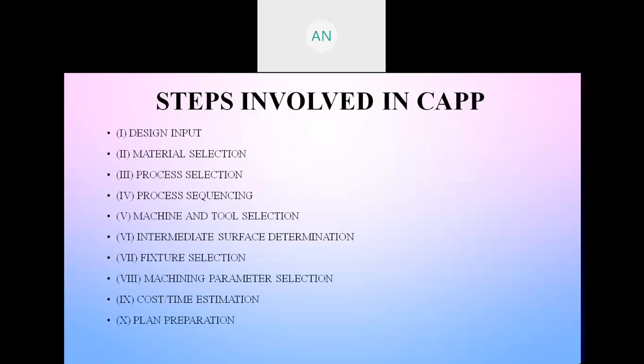So after the fixture design, suppose for example, we need 12 degrees of freedom to be locked on a fixture. There it could be optimized with a CAPP model where, due to the usage of the 3-2-1 principle, instead of locking 12 degrees of freedom, you can lock only 6 parameters. This could also be possible in your computer-aided process planning technique.